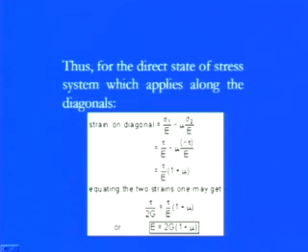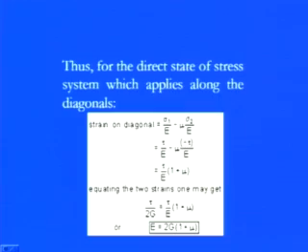So we have Young's modulus of elasticity due to direct stress and direct strain, and we have G, the shear modulus of rigidity, which is due to shear stress and shear strain. So we can set up the relation between the direct stress and direct strain component, the elastic component, if we know mu, the Poisson ratio. So we have E equals 2 times G into 1 plus mu.